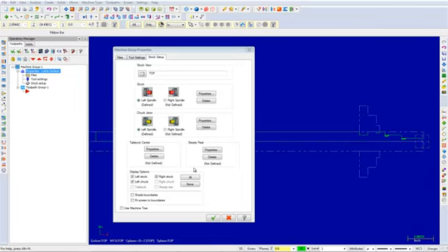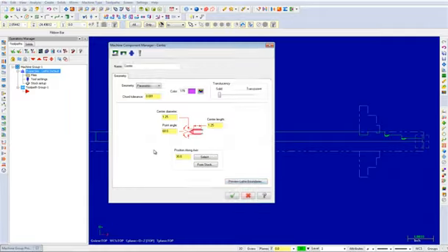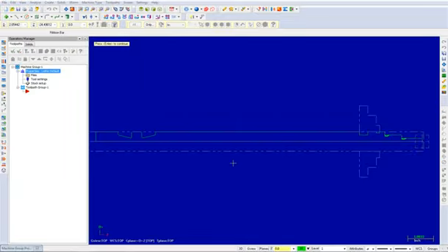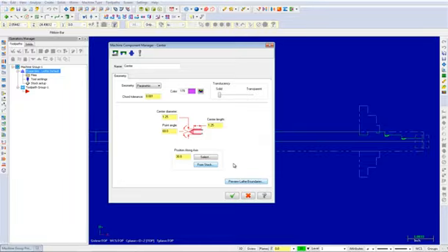In the tailstock center area, choose the Properties button. Now we will define the tailstock. Input a center diameter of 1.25, a center length of 1.25, and a point angle of 60 degrees. Also, set the position along axis to 30. Now select the Preview Lathe Boundaries button and ensure the part setup appears as shown. Press Enter to continue. Now select the OK button to exit the center dialog box.